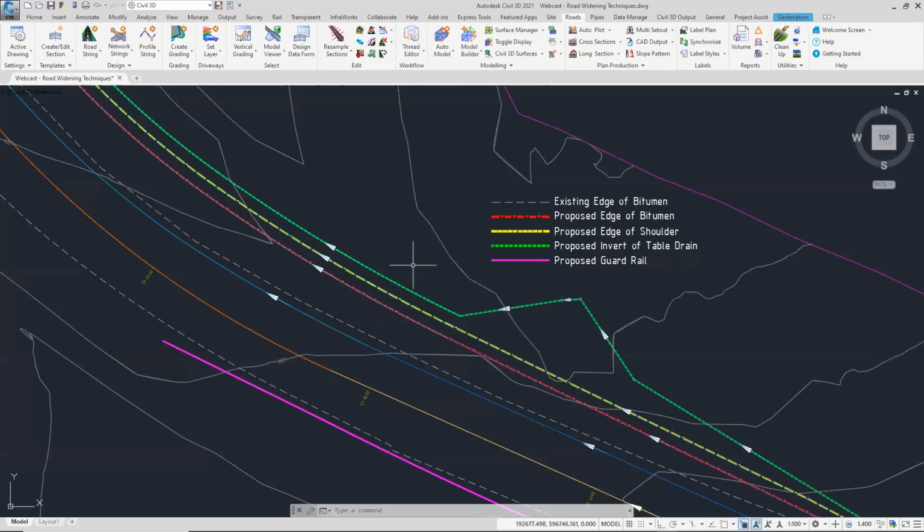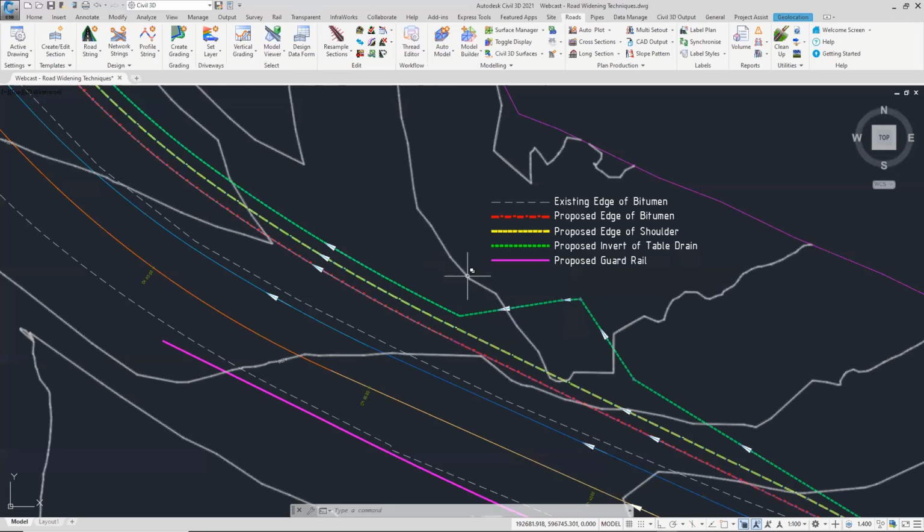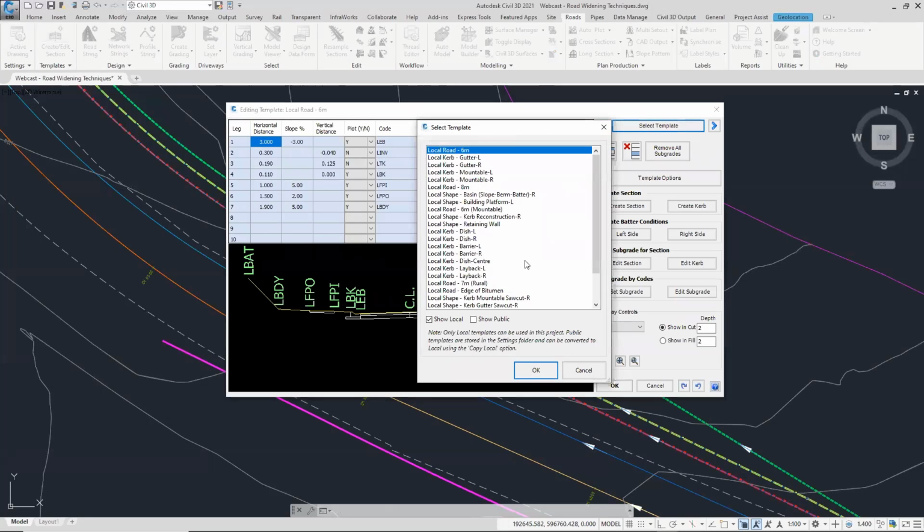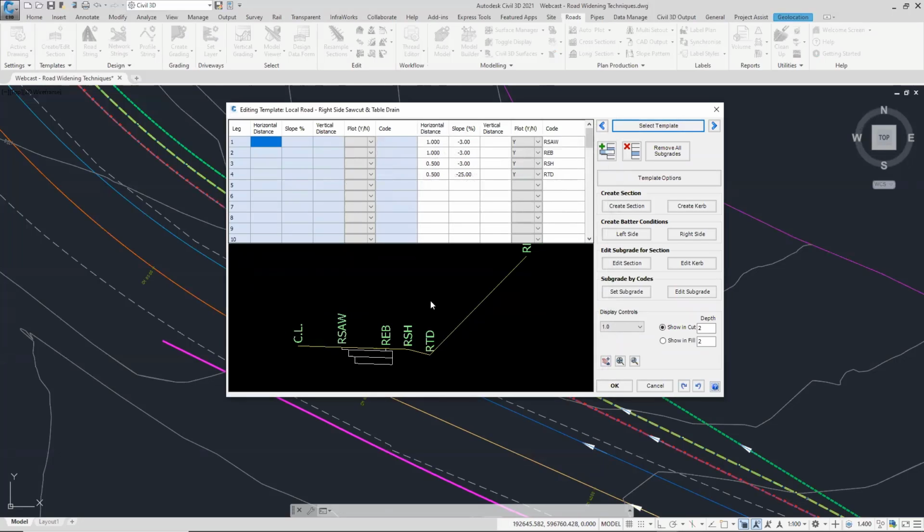Now, they're going to require fairly similar processes and plans of attack, but we are going to look at option one, do most of the digging in that one, and then look at option two, and a lot of the description and work will have already been done by that point. So we've got Civil 3D alignments in play here to help us depict all of these individual positions for the codes. What we've also done is created a template. I'm not going to sit here creating a template. We'll unpack the template that we've already created and explore it a bit rather than actually going through the creation process. So this is the template that we're going to be applying for option one.